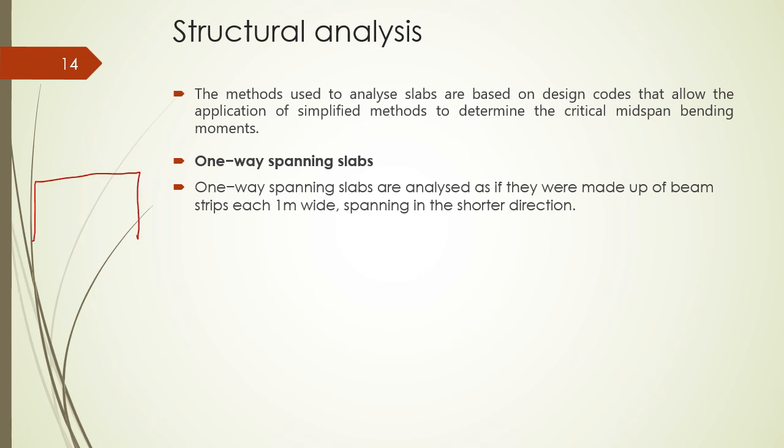This is a sketch of our one-way spanning slab. We will take a beam strip, we'll assume a 1 meter strip, and design for that.